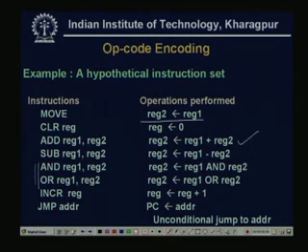Increment reg means the content of the register is incremented by 1. Reg plus 1 means 1 is added with the content, and then the value is stored in reg again. So, this is nothing but our add again, only here, instead of one register, one fixed value 1 is always added.